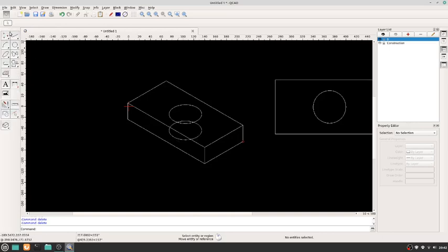So I'm going to use a really neat tool here. If I go into modification tools and I click on breakout segment, as you can see with some of these tools I've been going on, when I hover over it, it's got a little code at the bottom of it. For instance, this breakout segment, it says D2, which means rather than actually clicking on these tools, you can actually use those shortcuts. I could type in D2.